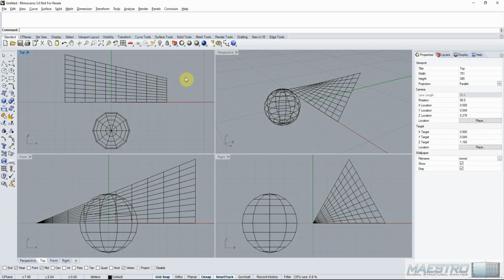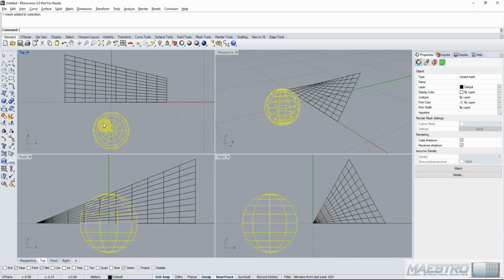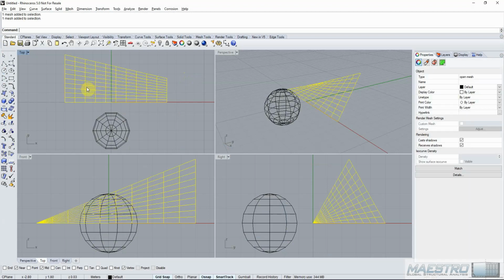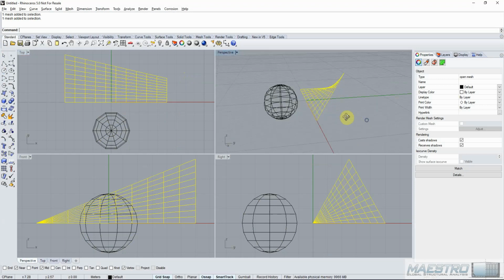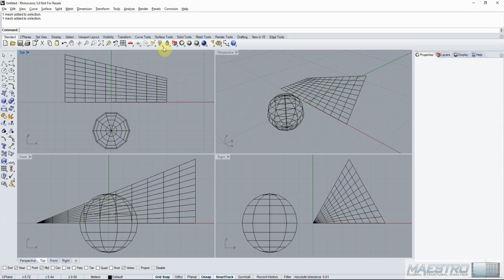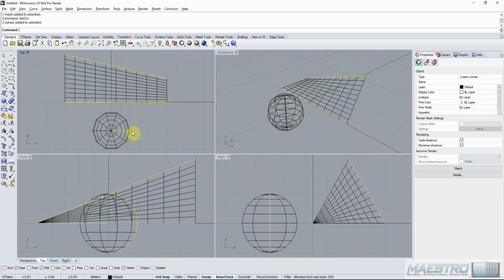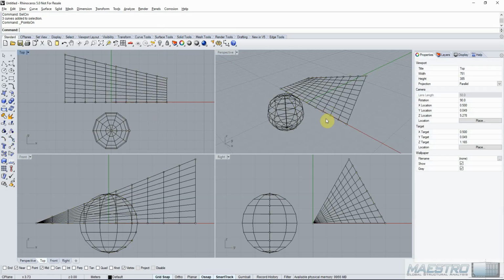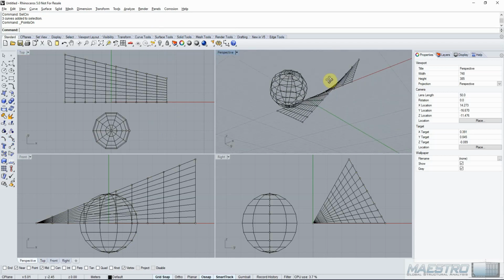To illustrate the second option, Polyline on Mesh, we've created two meshes, one a small sphere and the other a warped plane. The plane twists as it moves forward in the x direction, similar to how the shell plating might twist upward as it approaches the bow. For our curves, we created 3 polylines, one on the sphere and 2 on the warped plane. And if we turn the points on, we can see that the points defining the polylines correspond to the mesh vertices.